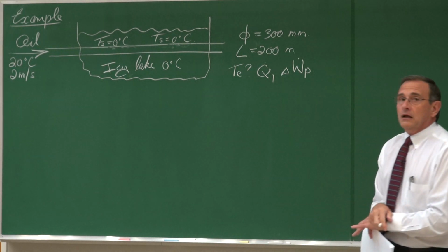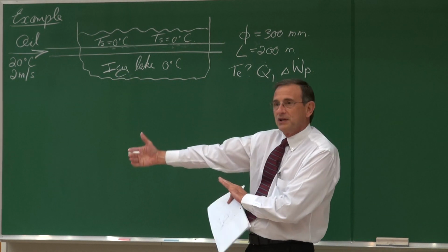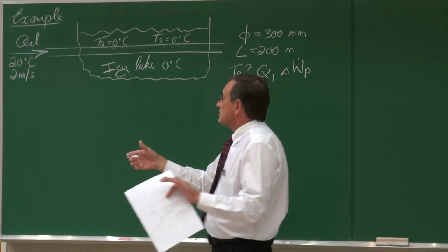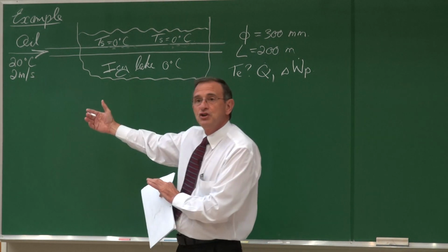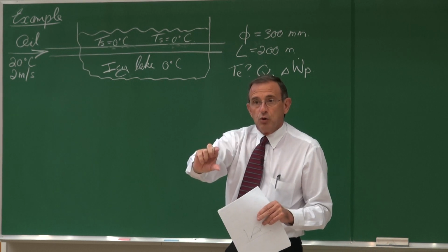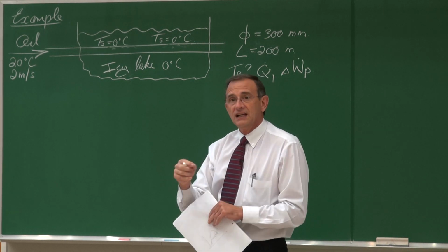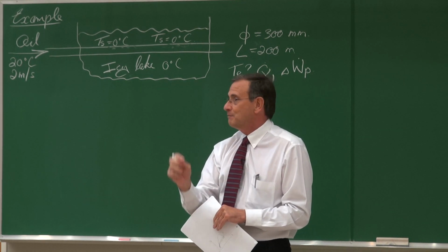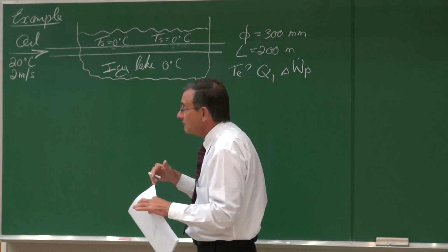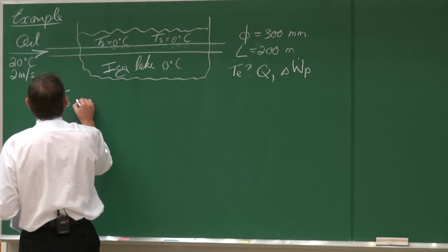Okay. Now, before we start these problems, we always need properties, like Cp, viscosities, etc. So the question is always, at what temperature do we get it? So I've already told you, go and look in table A13 in your textbook. At the bottom of the page, you will see, for example, the properties of oil. Can you see it? However, it is given at different temperatures. So the question is now, at what temperature must you select it? And as a guideline, we've given you the information that typically use the bulk temperature.